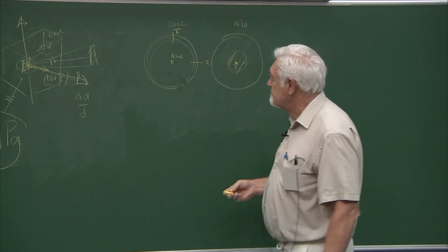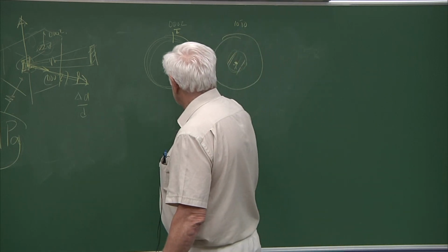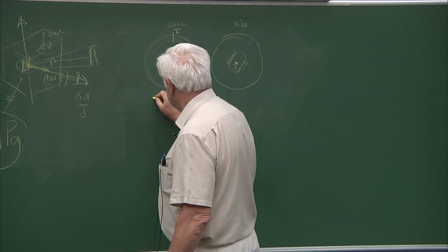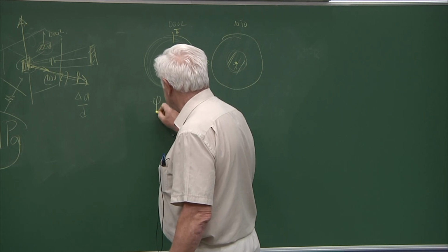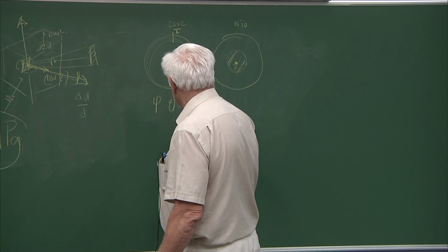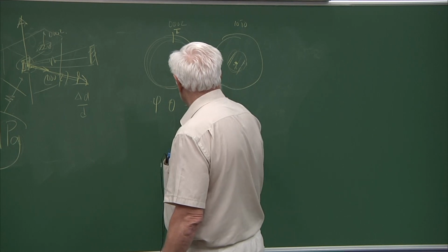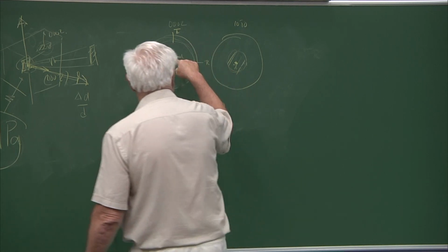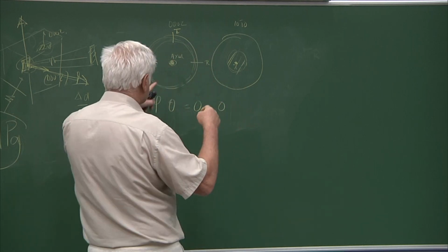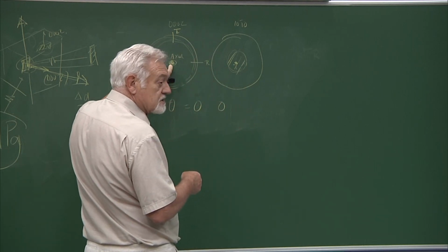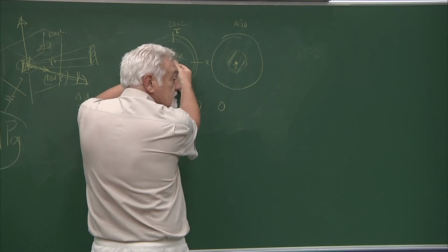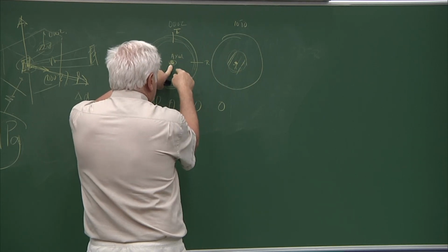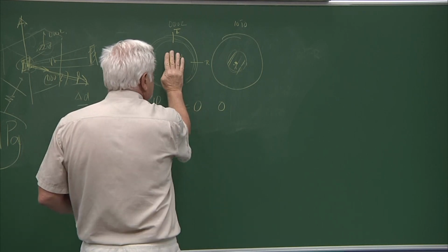Okay, the strains that I'm plotting: when those angles phi and theta that I gave are 0 and 0, you are orienting your sample so you are measuring the axial strains of planes that are perpendicular to the axial direction.